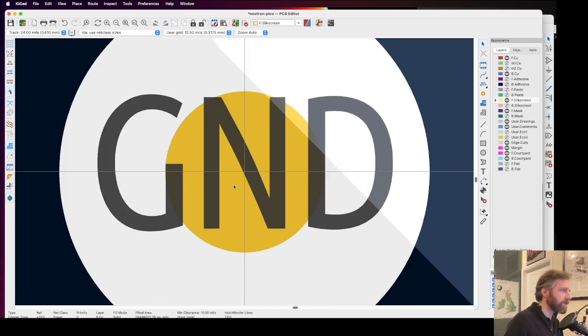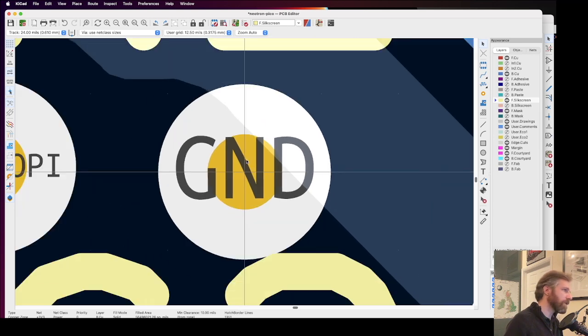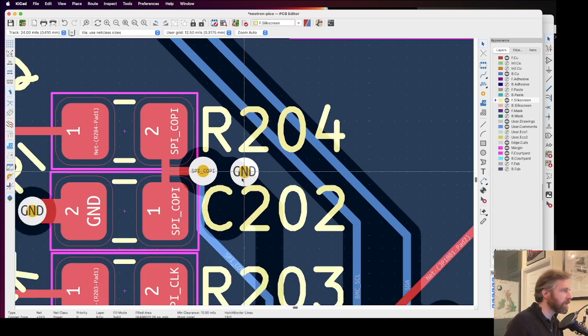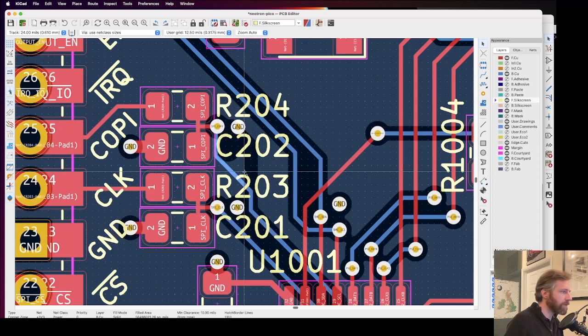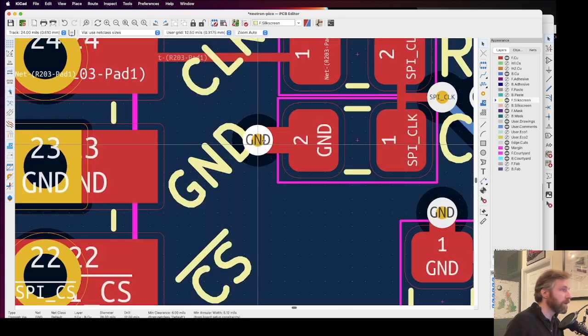It's only the yellow circle that is drilled. The white outer is copper plated. I don't think they're going to be drilling through silkscreen. Oh, well, not drilling through silkscreen. The board's already drilled. The problem is trying to paint silkscreen on top of a hole. The silkscreen will fall down the hole. There's another one.